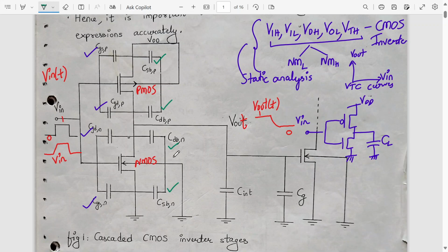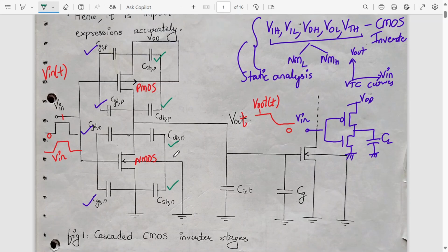So we'll see how much delay these capacitances are providing or affecting. If a pulse waveform is applied to the input, the problem of analyzing the output waveform is still fairly complicated, even for this relatively simple circuit. Right now, one CMOS inverter is driving another CMOS inverter, and a number of non-linear voltage dependent capacitances are involved. You see, four capacitances are involved right away.